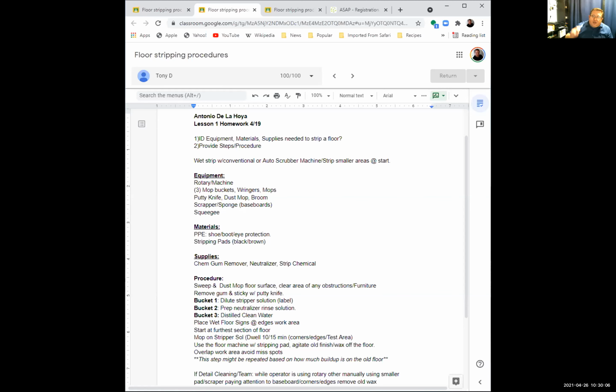So if it is laid out in such a way that the longer section has the longer part of the ceiling tile, the 4 foot length, and let's say there are 20 of those, you'd multiply 20 times 4 feet for the length of that tile. That gives you 80 feet. Then you turn around and count the tiles going the shorter section, and maybe that's another 20, but that's only 2 foot in width. So now we have 40 by 80.